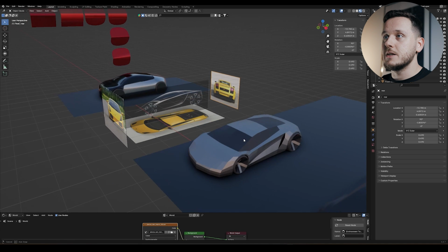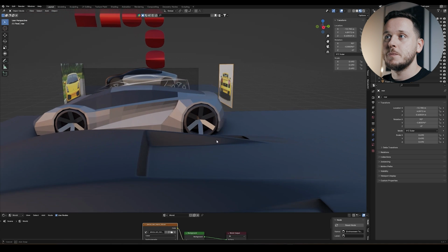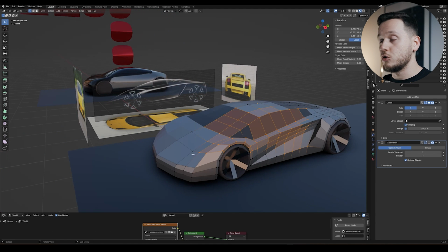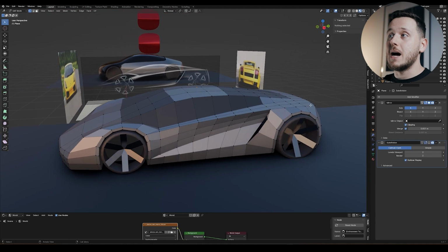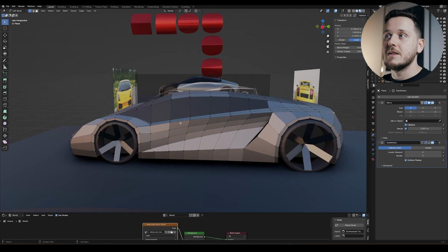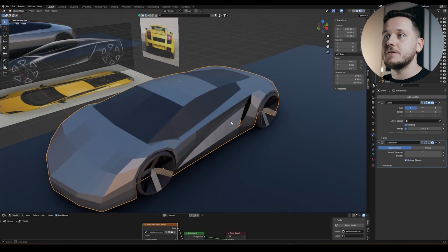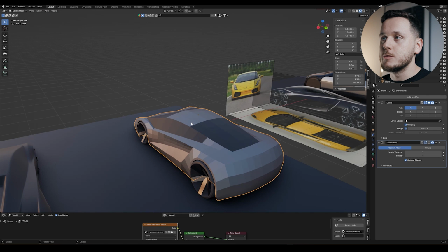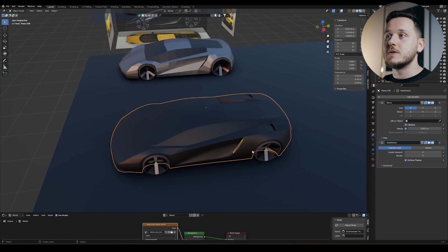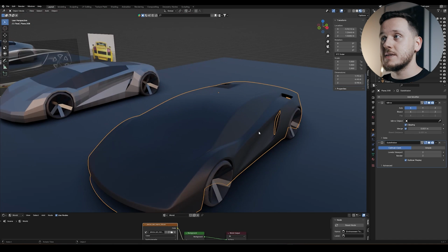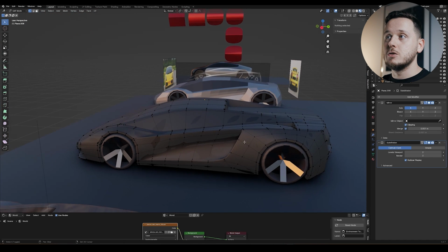And on the second day, we started by putting this sketch into the 3D basically. So I was using it as a reference. And here is a very simple topology, very simple volume, basically using the outlines of these edges from the sketch and then simply closing the volumes by creating the faces. So it's very basic, but after 2 days of workshop, the students were able to understand how to create the volumes of the cars. And on the third day, we already started to put the subdivision and putting some materials. Also, we did it, I think, before on the second day. And subdivision, shade smooth, and using some edge loops to bring the model into next level.